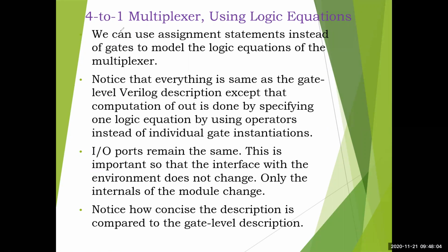We can use assignment statements here. The assign keyword is the basis of data flow modeling, used instead of gates to model the logic equations of the multiplexer. That's why I told you that till logic equations or Boolean expressions, I will write the design. Then it has a one-to-one correspondence with data flow modeling, which is nothing but assignment statements. We call everything here assignment statements.